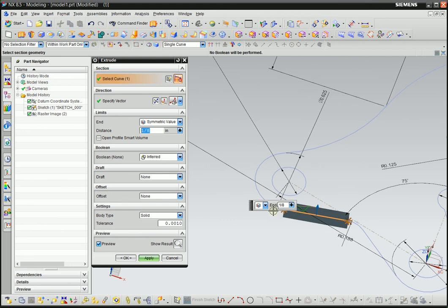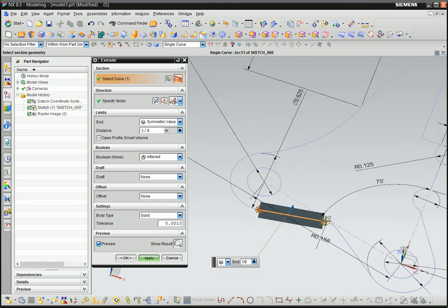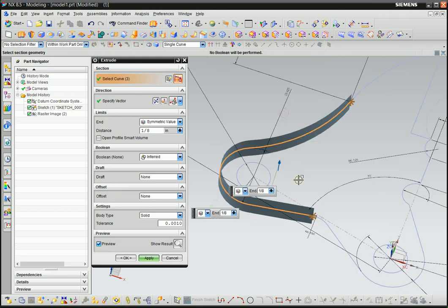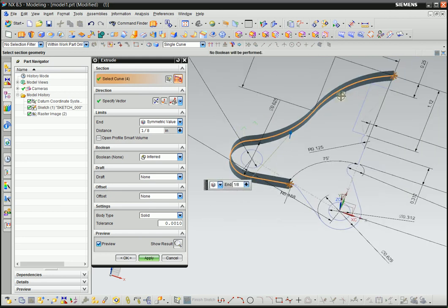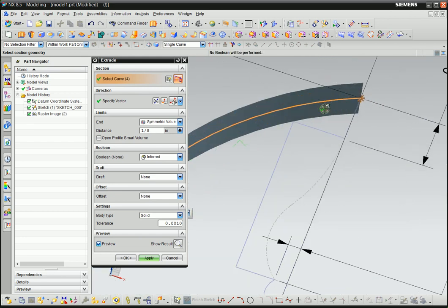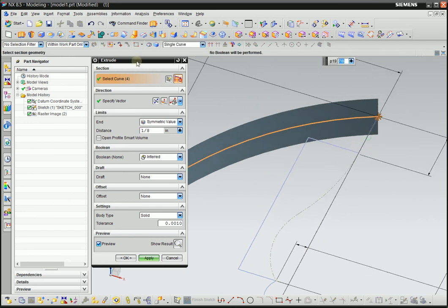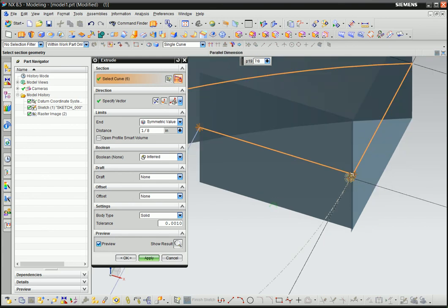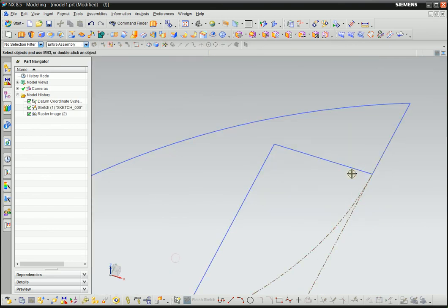And look at the star. The star means this open end, so we can keep selecting curves until you see something wrong. Then you can find the problem. See, you see that two stars? That means the sketch is not good here.